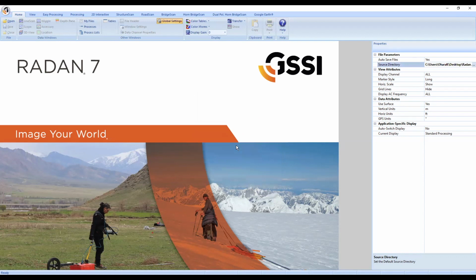All right, so we've now told RADAN where to look. Because we're using a pre-assembled 3D grid, this part does not matter at this time. But I'm pointing it out now because when we assemble it in RADAN, it's very important that after we set our source directory, we take a look at, at the very least, the horizontal units and set them the way that we have our grid notes, right?